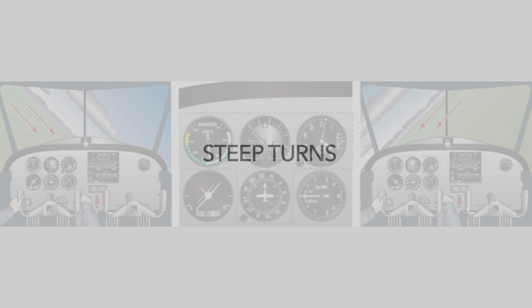There are several things to consider when executing a steep turn. 1. As angle of bank increases and/or airspeed decreases, the radius of turn decreases. The opposite is also true. 2. When rolling into a turn, there will be a gradual loss of the vertical component of lift, which will require the addition of elevator back pressure to increase the angle of attack.